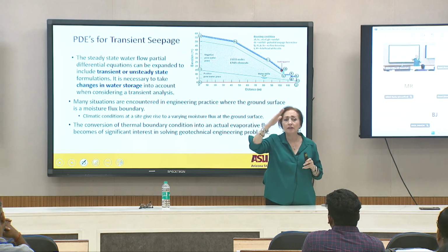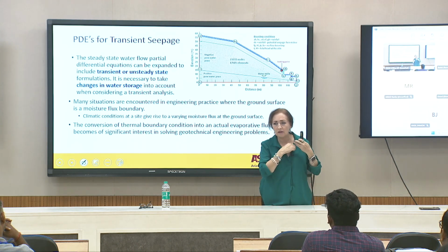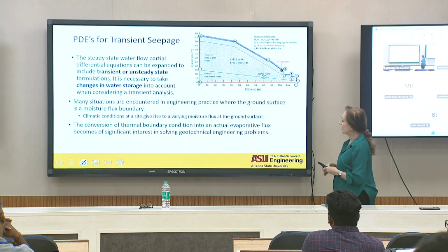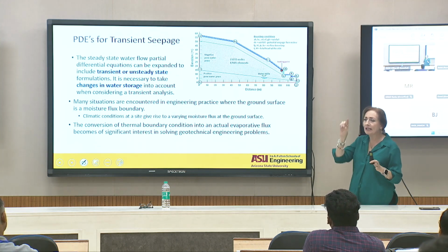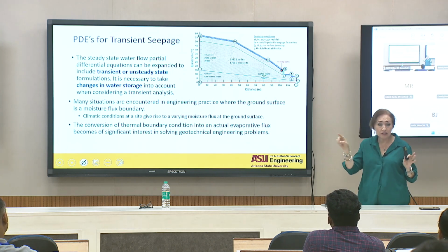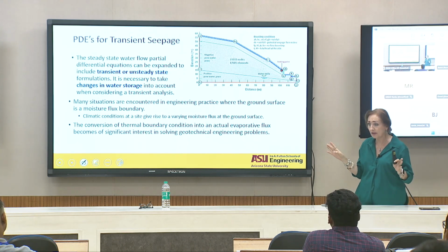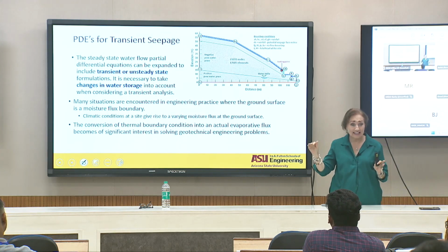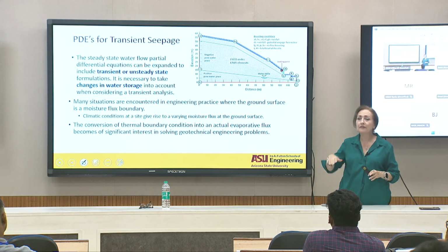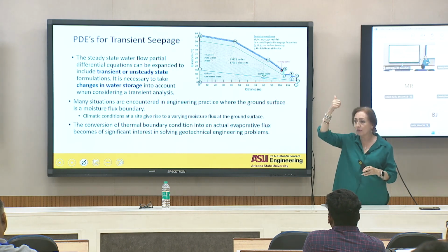If you want the groundwater table to fluctuate, then you need to use another condition. So you set up your program, and you first set up very carefully what boundary conditions you need to work with, whether there is no flow here, or a constant head condition, or some influx or evaporation going on.